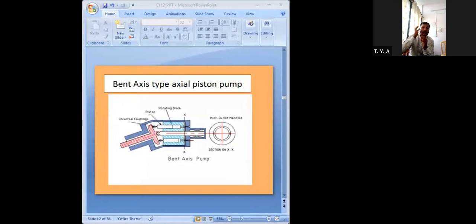When the piston carrying body turns, the exit passage in the cylinder, that is the bore, will move along the control slots of the positional control. Alternately, suction and discharge will happen in the suction and discharge pipelines.